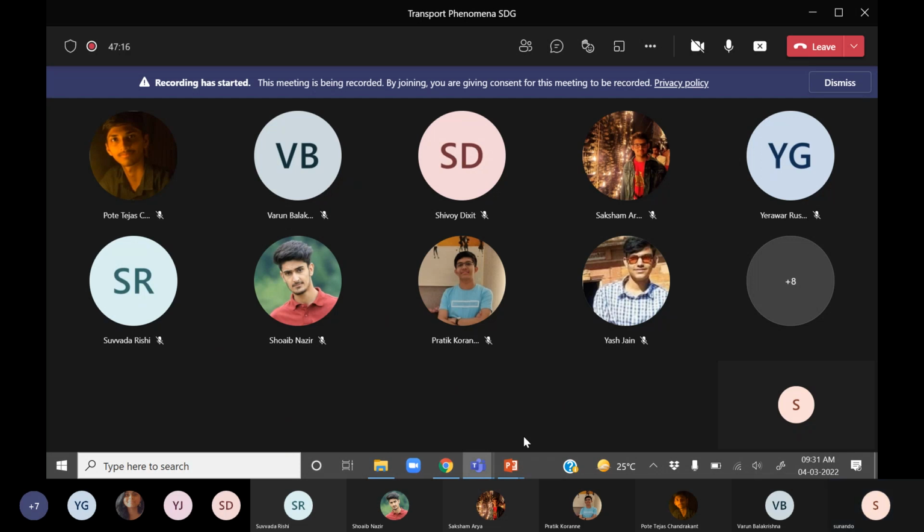So if we agree that is the approximation which we can adopt, can anyone else tell us something, how do I choose the lubricant? You all are aware that a lubricant works best within a certain temperature range. If you go beyond that temperature, whatever that temperature is depending on its constituents, it will lose its lubrication property, which is known as the breakdown of a lubricant. So it will not act as a lubricant, it will degrade. So you have to be very careful about the choice of the lubricant. Now can you answer?